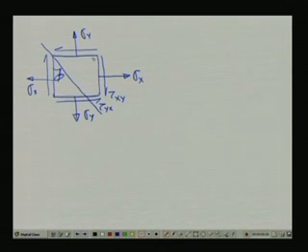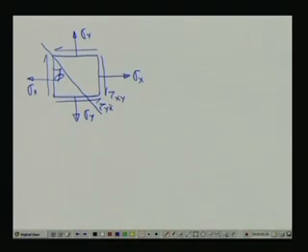Now this will create a situation that at any particular cross section we can have stresses of different kinds. Similarly it holds good for the shear stress: if we see a shear stress acting on this plane in this manner, for any other orientation or any other plane, the shear stress can also take a value which could be much larger than this value or also lower than this value. So let us examine and find out what physically it means.